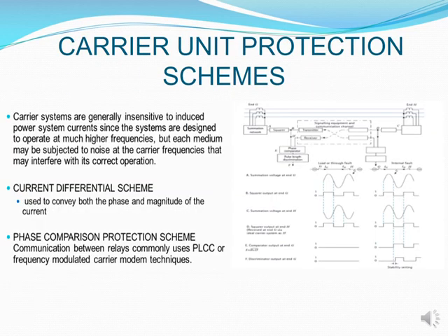Then we have carrier unit protection schemes that can also be utilized on our line feeders. These carriers are generally insensitive to induced power system currents, since the systems are designed to operate at much higher frequencies. But each medium may be subjected to some noise at the carrier frequencies that may interfere with correct operation.